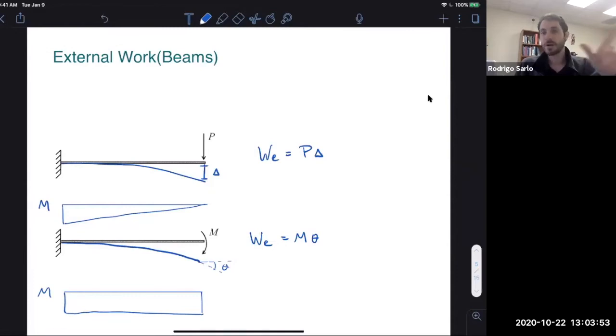Okay, so that's what we're not doing in this class. We're avoiding it because for what those methods give us, they tend to be overly complicated, right? Generally we don't want an equation for the deflection. We generally just care about where the maximum deflection is occurring. And I strongly think that by just drawing a qualitative deflected shape and then isolating the place where you think the maximum deflection is, or isolating a few places, you can then just use the method of virtual work to solve for those deflections, and you're okay, right?